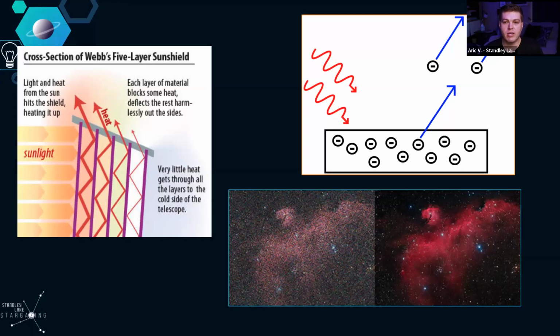So if you want to be looking at infrared, for example, you need to find metals that are responsive to the wavelengths of infrared light and that generate a voltage in return. My understanding is that the CMOS sensors have a much shallower penetration into the infrared, whereas CCD detectors are first of all easier to cool, and more reliable nowadays just because the engineering expertise has increased. But also the materials that are responsive to those different wavelengths are just easier to manufacture as a CCD than the more limited CMOS.